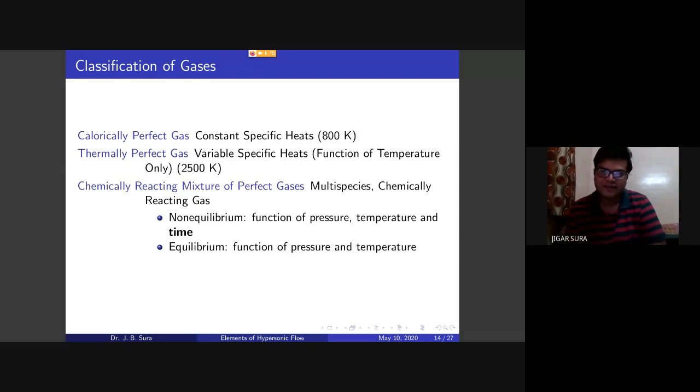So in the given control volume, if you have 20% oxygen coming in, the same 20% of oxygen should go out in some other way, not necessarily as an oxygen molecule. It can be in terms of CO2, H2O, NO2, N2, or any other nitrates.